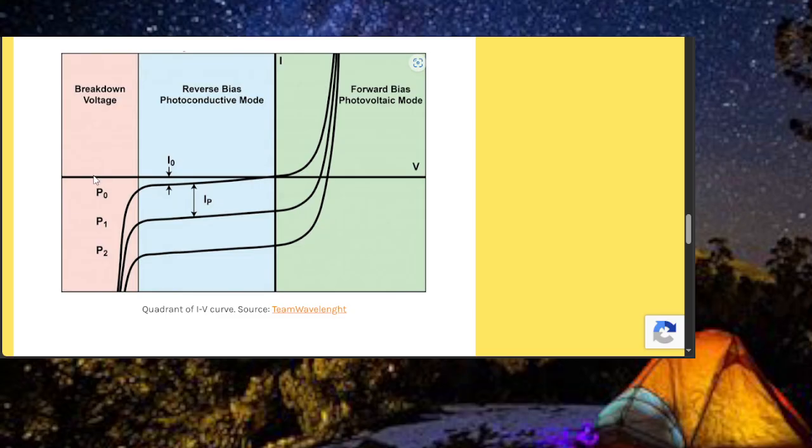If the voltage across the diode is reversed and it's a large enough voltage drop, then all of a sudden this thing will go into breakdown avalanche mode, and if it's left too high it may destroy the diode. When you put it back in its normal state, it won't run again because the depletion region is messed up. That's FUBAR, beyond repair.